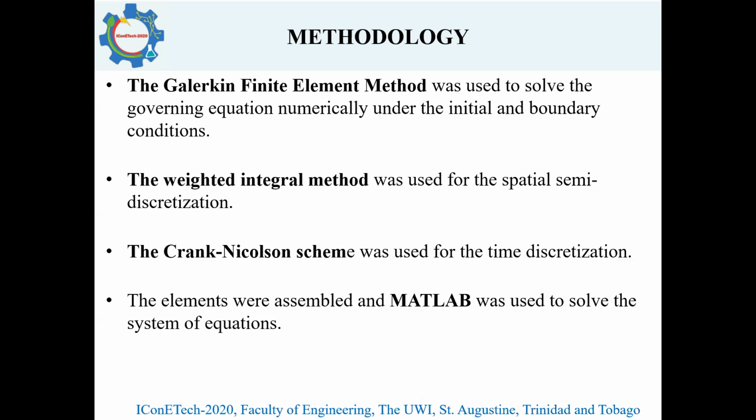To do this, the Galerkin finite element method was used to solve the governing equation numerically under the initial and boundary conditions. The weighted integral method was used for the spatial semi-discretization. The Crank-Nicolson scheme was used for the time discretization. The elements were assembled and MATLAB was used to solve the system of equations.